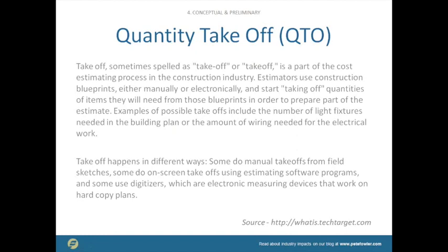And we have to think about the material and the format it comes in. If I was going to use vinyl flooring that came in rolls 10 feet wide by 60 feet long, but I've got a room that's 12 feet wide by 20 feet long, how am I going to do the seams? What am I going to do there? Do I want a 2-foot strip, or do I want to cut it down the middle and use more material? You've got to figure it out.